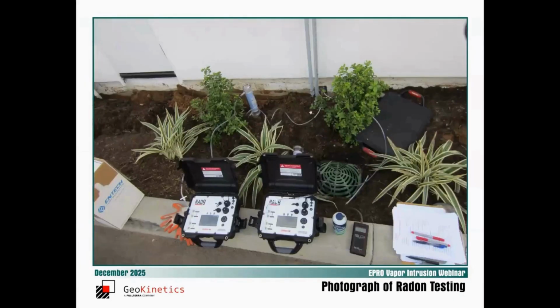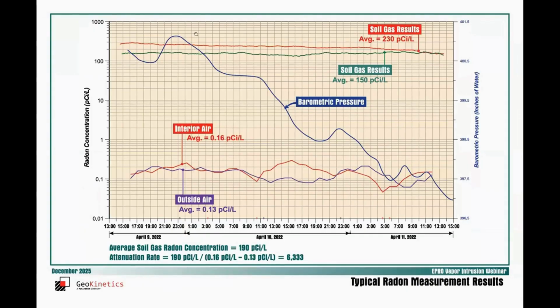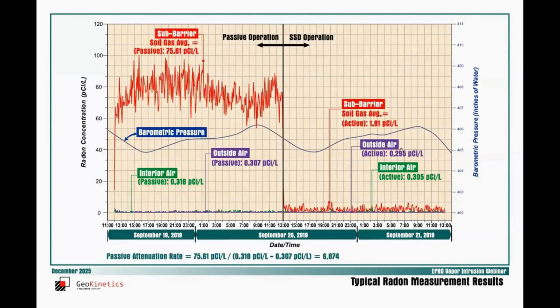Typical gas probe connections, we usually terminate them in the foundation stem wall. Typical results, soil gas levels up here, around 150, 200 picocuries per liter, indoor and outdoor air down here. And we measure the barometric pressure, and a dropping barometric pressure curve like this is ideal because it tries to force VOCs to the indoor air.